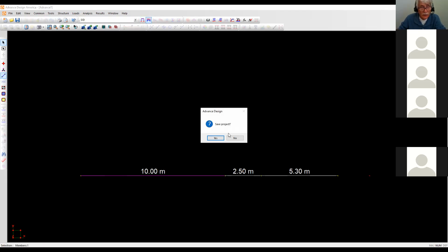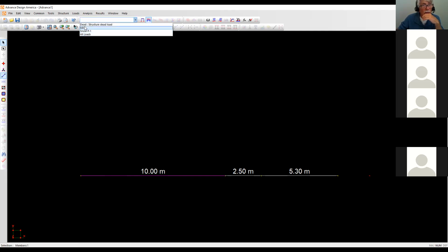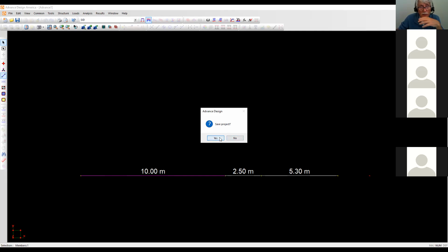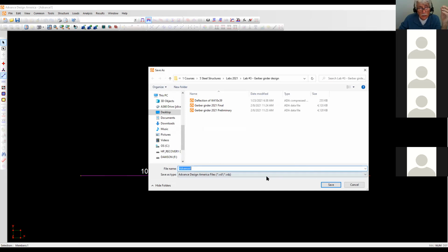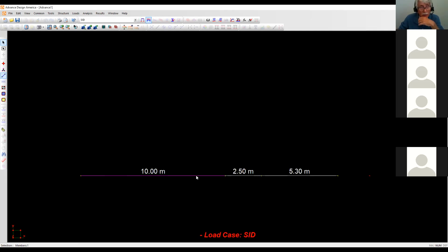Okay, so now I'm going to go to my loads. I'm going to do a superimpose dead load. Now I'm going to double click on the member. I've got to pick superimpose dead load. It's going to ask me, okay. Anyway, I'm going to double click on the member.